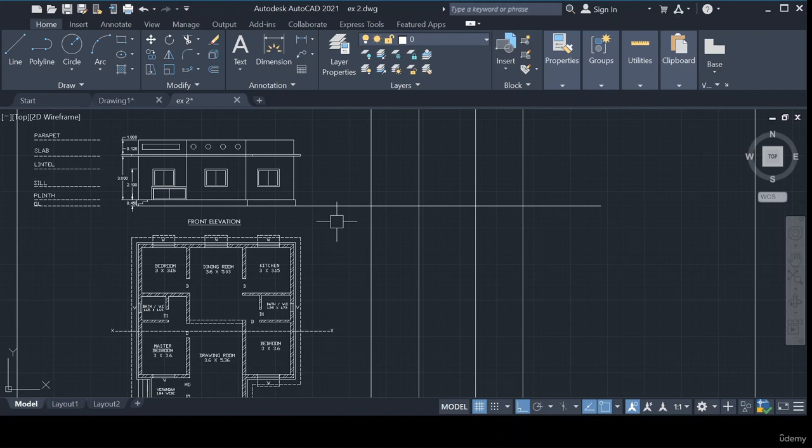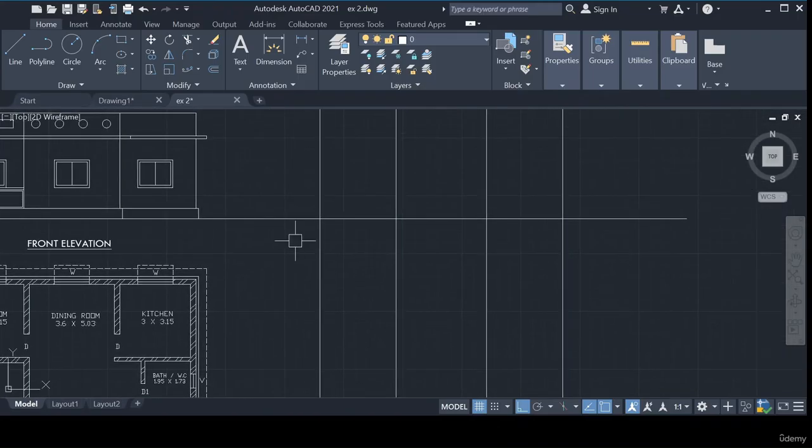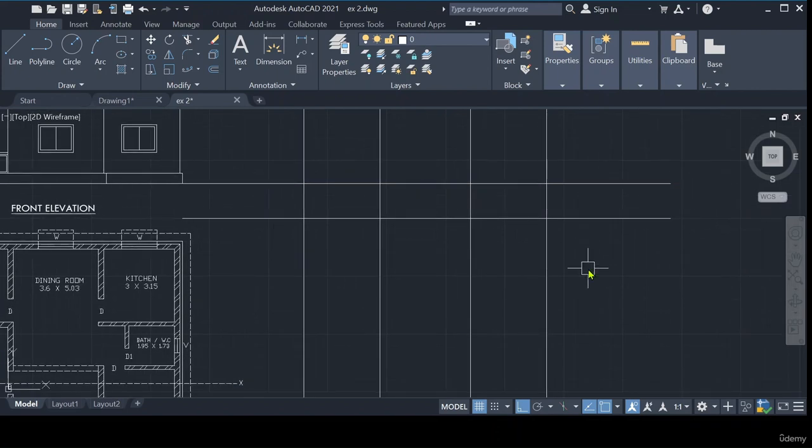Depending upon that, we need to go for the excavation depth of the foundation. Normally, as per the standard, we need to go 1.5 meter or up to the hard strata for the excavation. So minimum we need to go for the excavation is 1.5 meter. So I am considering 1.5 meter. Offset, I just enter 1.5 meter. So minimum depth of the foundation is 1.5 meter. I just delete this one.